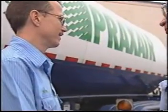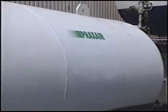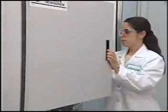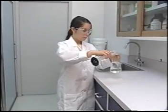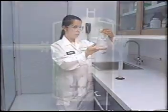Because carbon dioxide has no color or odor, your senses can't always tell if it's present or how much is in the air we breathe. Releasing carbon dioxide outdoors may not create an asphyxiation hazard as long as air circulation keeps oxygen levels high enough. But indoors, especially in low areas or confined spaces, carbon dioxide can force out oxygen. That means anyone inside these areas risks asphyxiation.